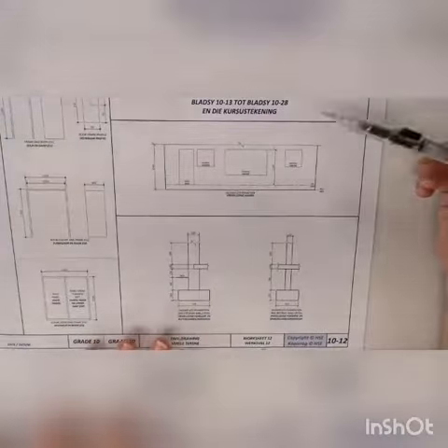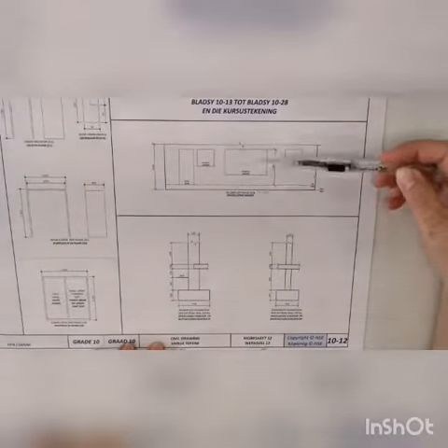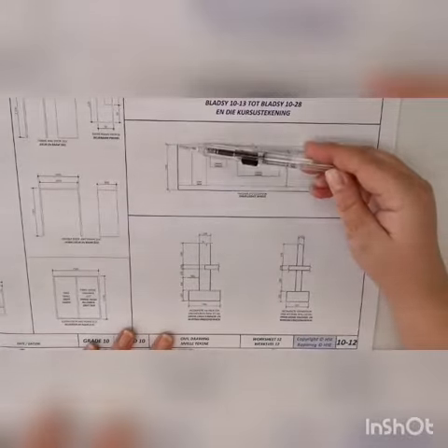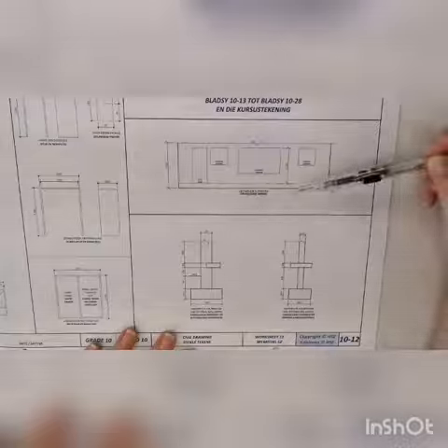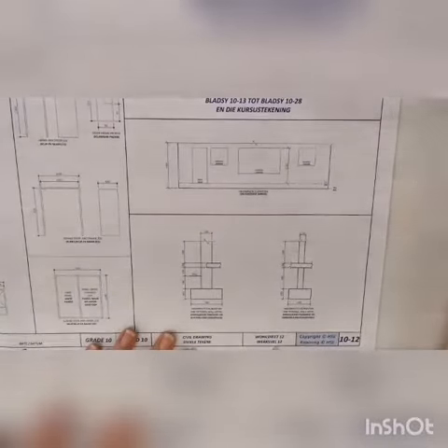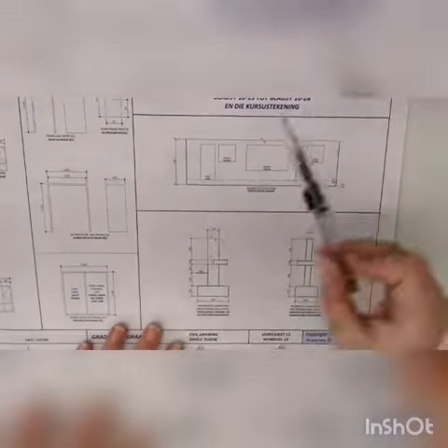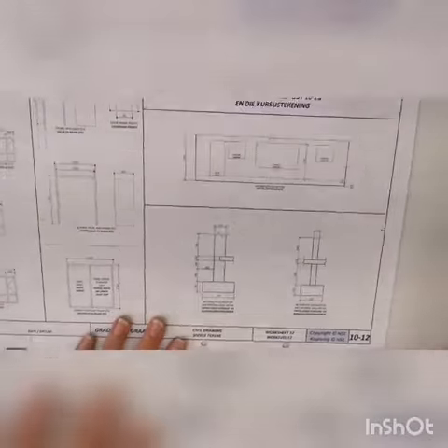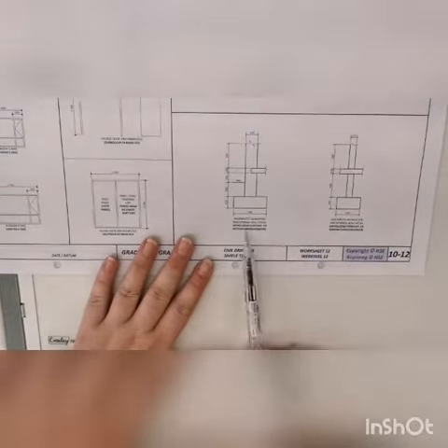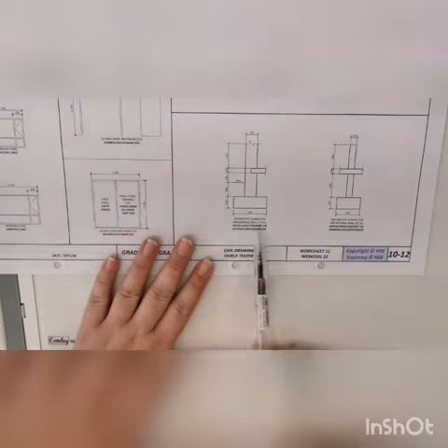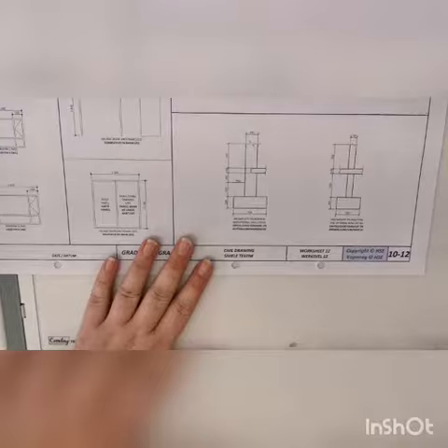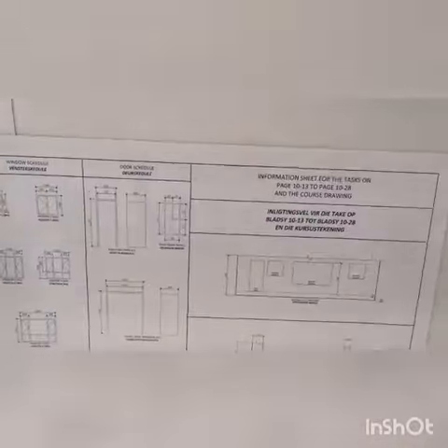Okay, here's an incomplete elevation. Here they've given us again from the natural ground line to the top of the wall, as well as from the finished floor level to top of any doors and windows. Doors and windows sit on the same line up here. Then they've given us an incomplete foundation with all the measurements. We're not going to use that just yet. Right, let's go back.